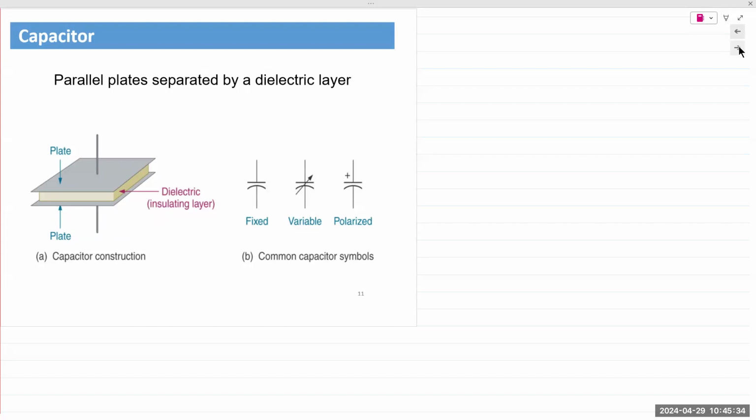You could take a simple coaxial cable that has two conductors. They are separated by an insulating material. There is capacitance present between those two conducting materials. That capacitance does not rise to the level of interference. If it goes long, maybe let's say 15 feet, 25 feet, or 50 feet, then yes, it does rise to the level of interference. But again, any two conducting materials separated by an insulator, you have a capacitance.